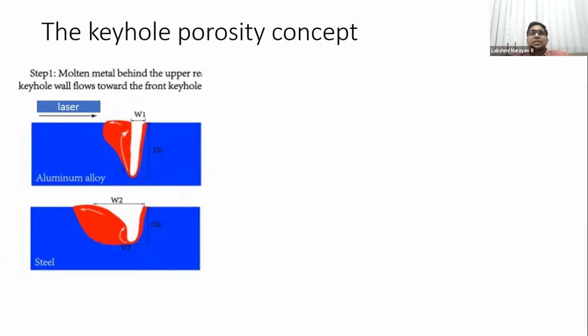What really happens is that the melt that has formed on one side, because of the injection pressure, or you could say the pressure created by this melting, is going to make the melt pool on the side of the melt come back like a wave. Okay, so this is the back pressure that is applied. So there is a back pressure when you're doing this melting. You're going forward, and there is a melt pool back pressure.